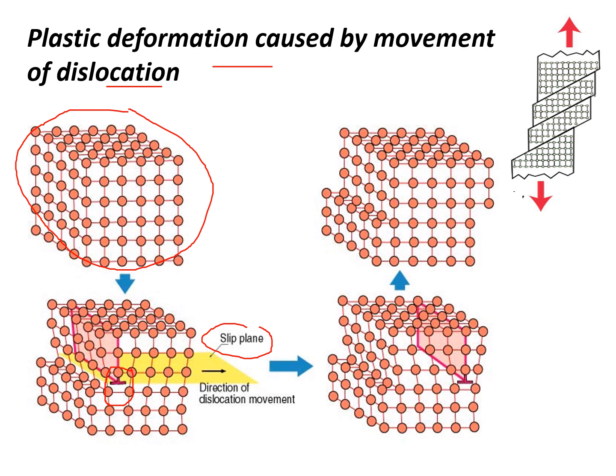Now further, if you apply the load, then this dislocation will move. You see this dislocation moves like this. So this is the initial one. We are getting this dislocation of the slip plane. Then this dislocation will move like this. And this is the phenomena of the plastic deformation.